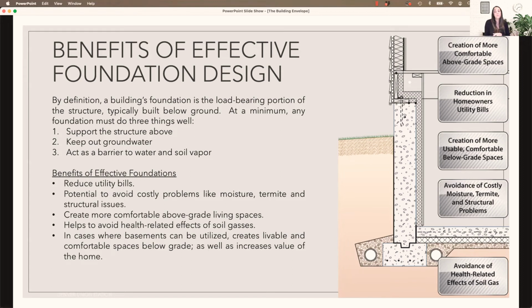We're going to talk about soil vapors when we get into indoor air quality, but there are vapors and gases within the soil that can seep into buildings if they're not properly maintained or don't have the proper barriers in place. So those vapor barriers are extremely important, not only in keeping buildings dry, but also in keeping those toxic gases out.